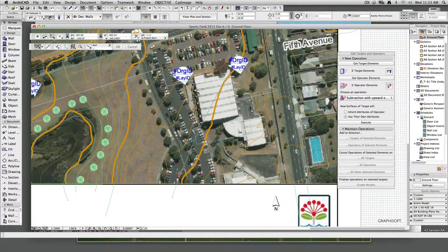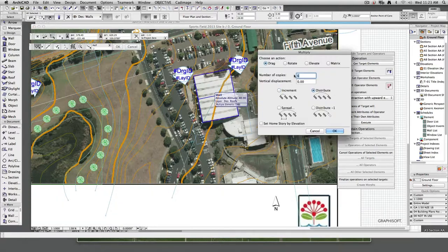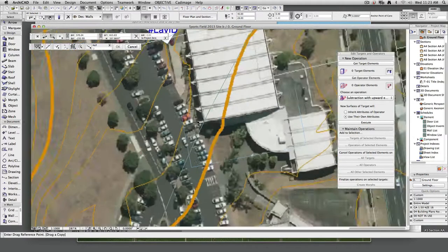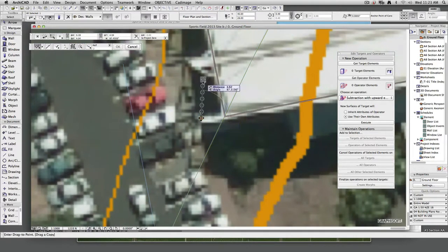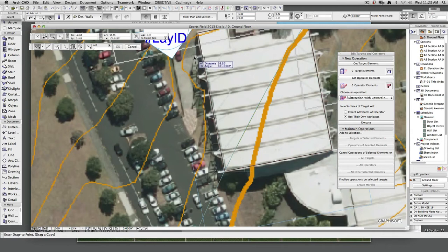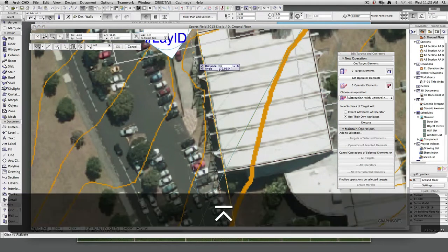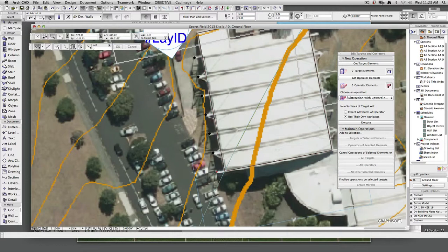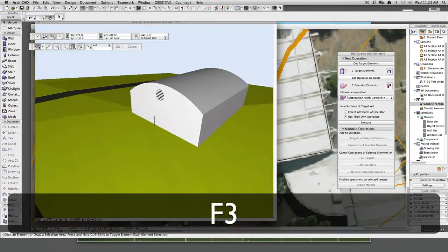Okay. I could have actually, in fact, a better way to do it is if I go Command U, distribute 6 of them. I'll reduce my error then across this distance. Again, see, if I wanted to be nice about this, I could go, okay, let's do 36 meters parallel to this, and make sure we're running parallel. Cool. And let's go D36. Beautiful. So that looks like that.